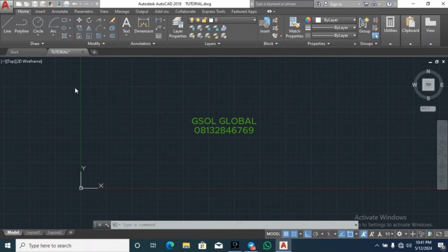You can see the y direction, the x direction, and the graph is divided into grids, and inside those grids there are smaller grids. Each main grid is either 1 centimeter or 2 centimeter. AutoCAD by default has 1 centimeter, but I don't think it's cool working with a 1 centimeter grid. Let's work with a 2 centimeter grid so that we set it right away.